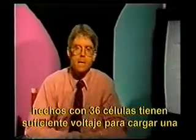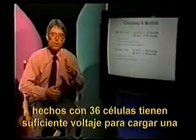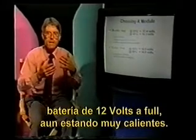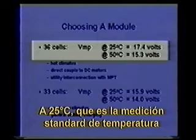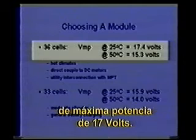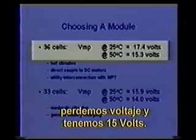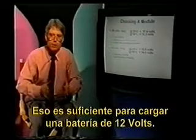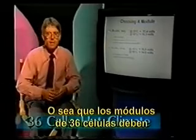Modules made with 36 cells have enough voltage to fully charge a 12-volt type of battery, even when they're very hot. At 25 degrees C, standard room temperature measurement, our 36-cell modules have a max power voltage at around 17 or so volts. When they get hot, up to about 50 degrees, which isn't untypical at all, we lose some voltage and we have about 15 volts. That's enough to charge a 12-volt battery. So 36-cell modules should be used in the most hot of climates.